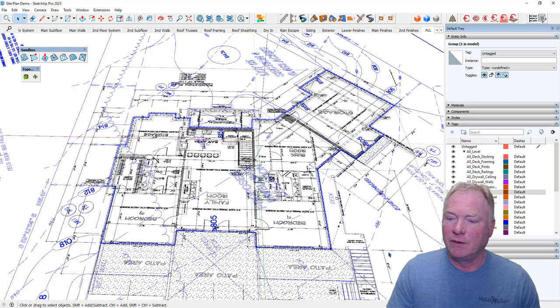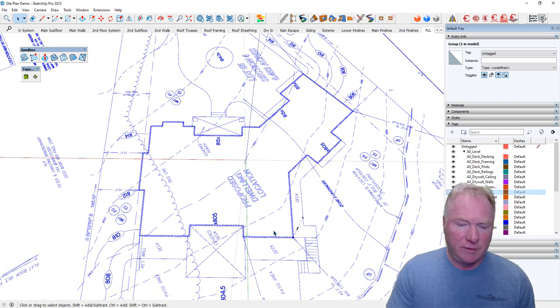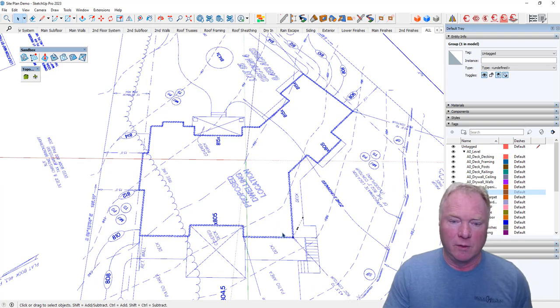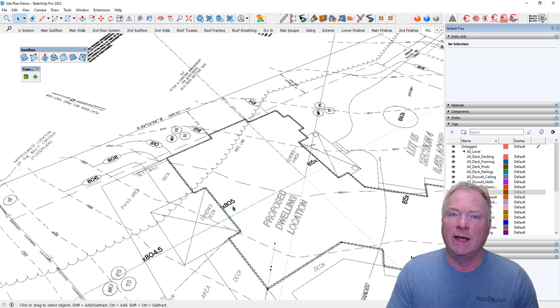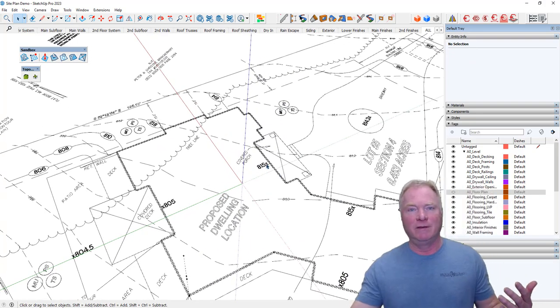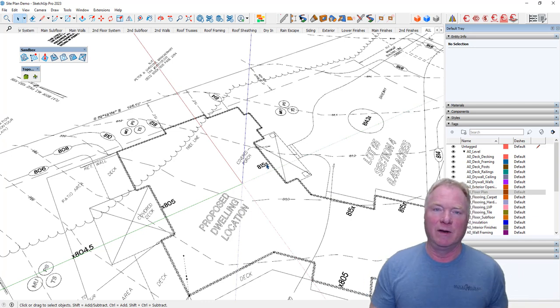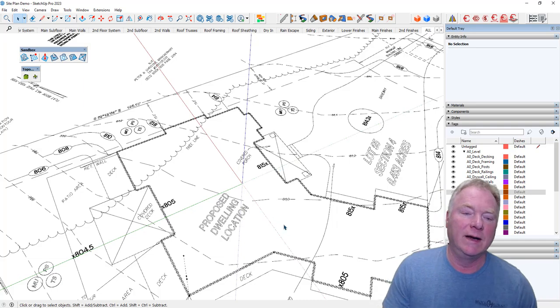All right, so in looking at this plan, I'm going to cut off the floor plan just for a second. You can see here that they have called for what looks to me like the basement elevation is 805, and the front 815. Convenient that it's just 10 feet. I mean, it's going to vary depending on what we just did in that story pole. But we're going to use the 805 for right now.